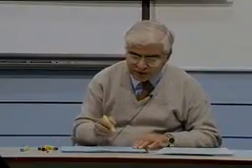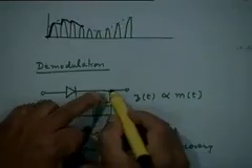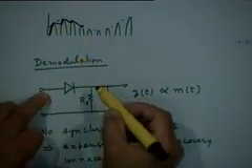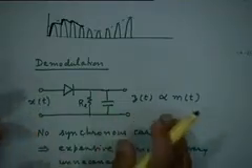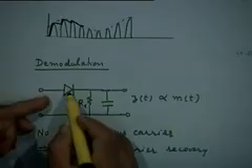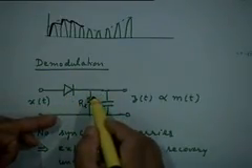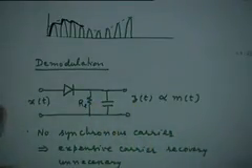Yes, please. Sir, why are we saying that the diode will not conduct while the peak is falling? Isn't that obvious? The question is, why would the diode stop conducting in this interval? That's because the voltage here at the output is now higher than the input voltage, right? When does the diode conduct? Suppose this is a PN junction diode, if the P side is at a higher voltage than the N side, right, then only it conducts, isn't it? It's a very elementary operation of the diode.